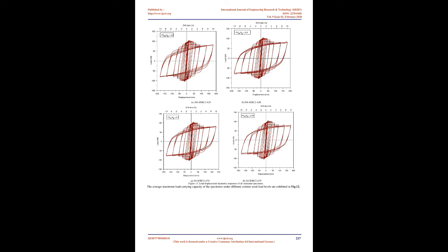The average maximum load obtained from the NLFEA analysis was 3.35% lower than the average maximum load reported from the experimental study, refer to Table 5 for comparison. From the above figures, the ABAQUS models show the envelope curve precisely. However, the hysteretic loops of the ABAQUS models, as compared to the test results, exhibit a fat pinching distance, as expected from the embedded method of concrete and reinforcement modeling. This pinching distance clearly describes that the tension stiffening is an approximate consideration of the bond slip effect in the modeling, due to the adoption of the embedded, perfect bond, method to simulate the bond between reinforcements and concrete.